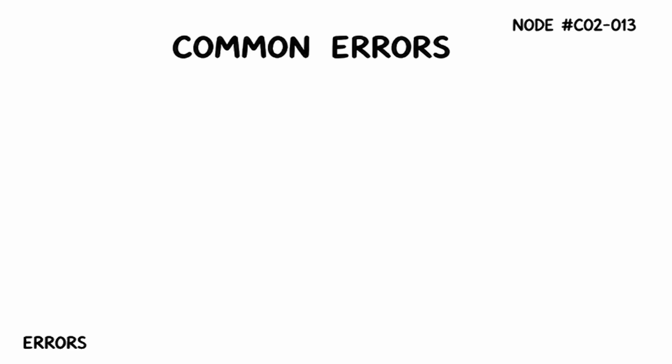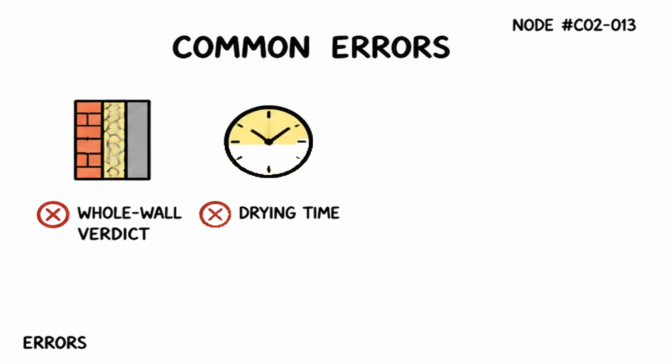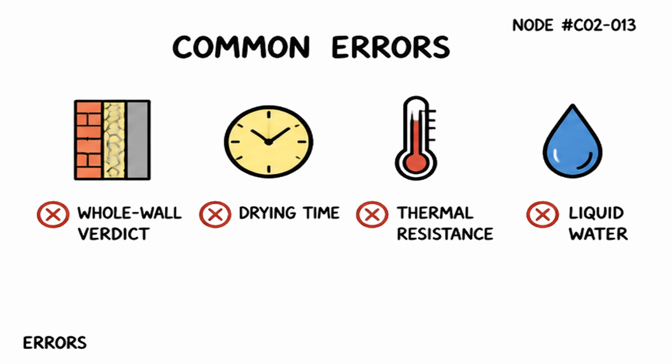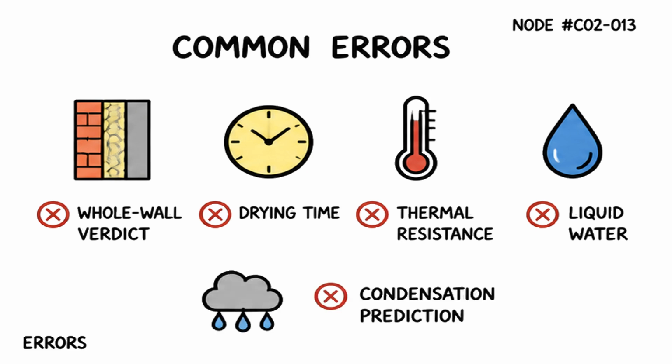Common errors. SD alone does not judge the whole wall. It is not drying time. It is not thermal resistance. It is not liquid water resistance. And a single SD value does not predict condensation on its own.